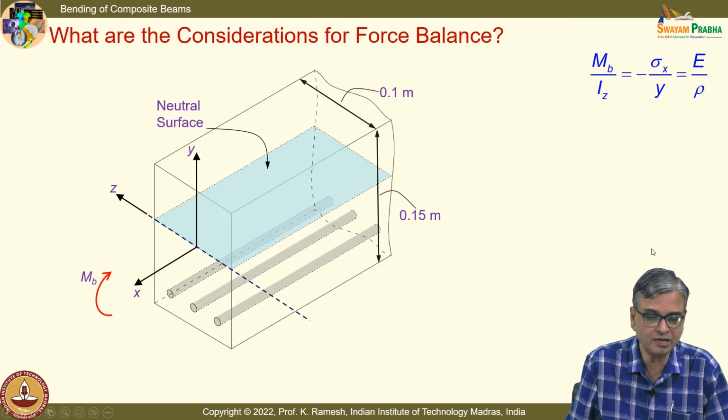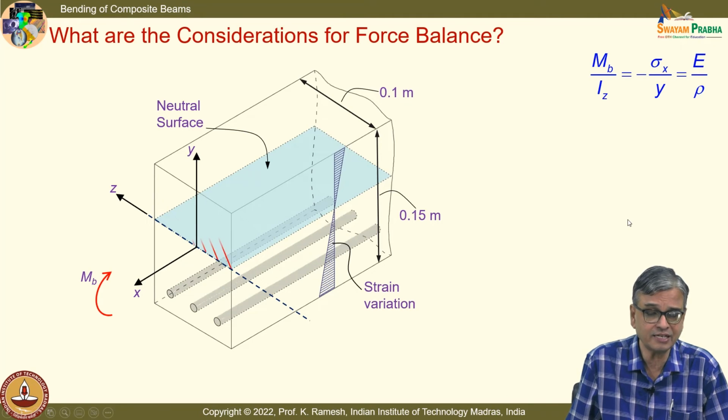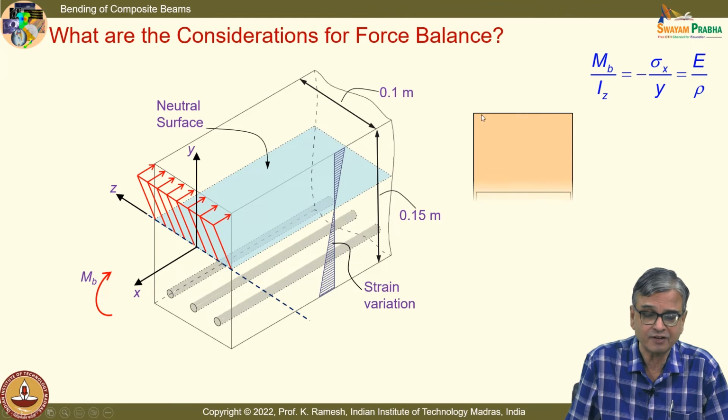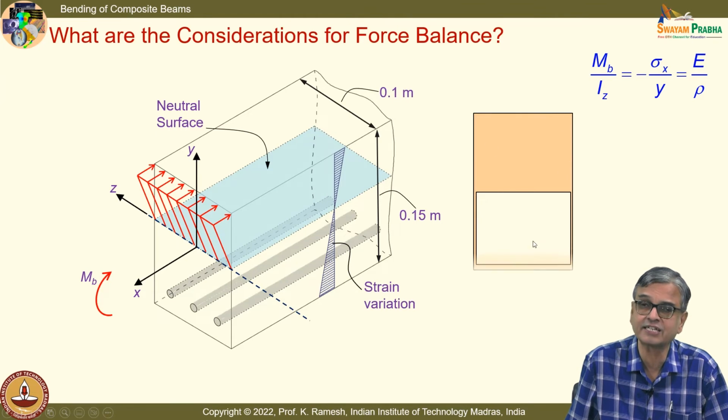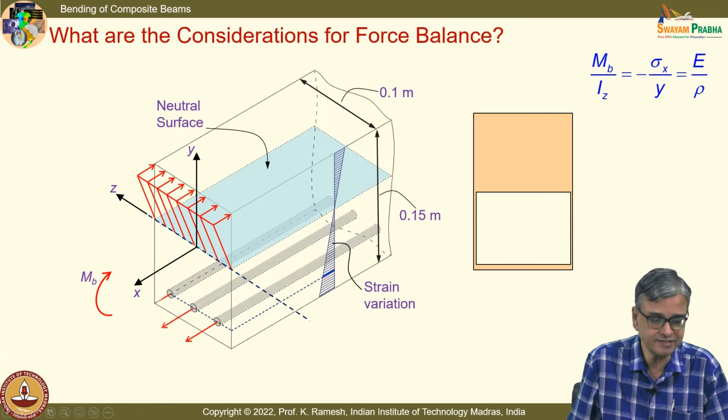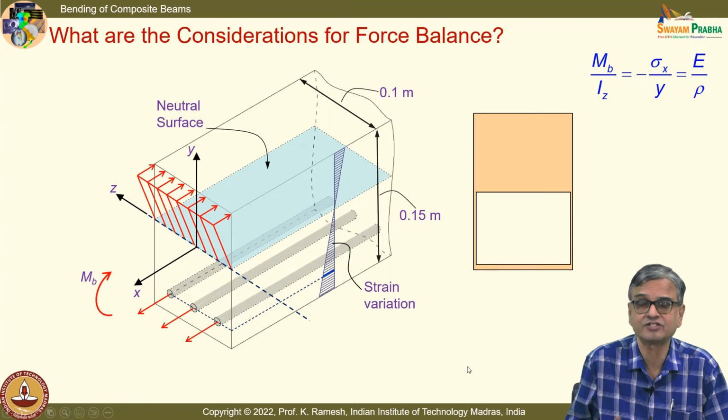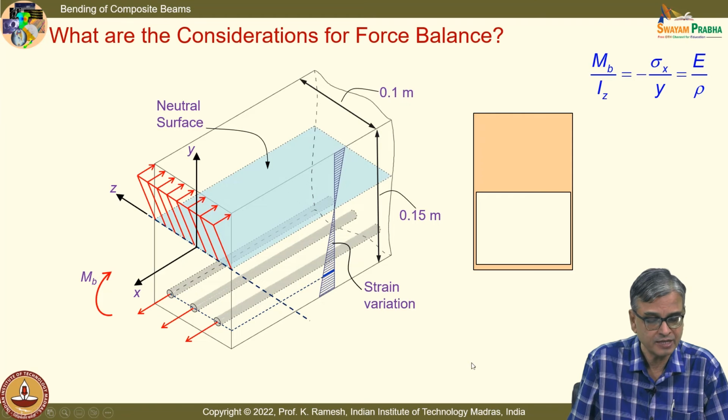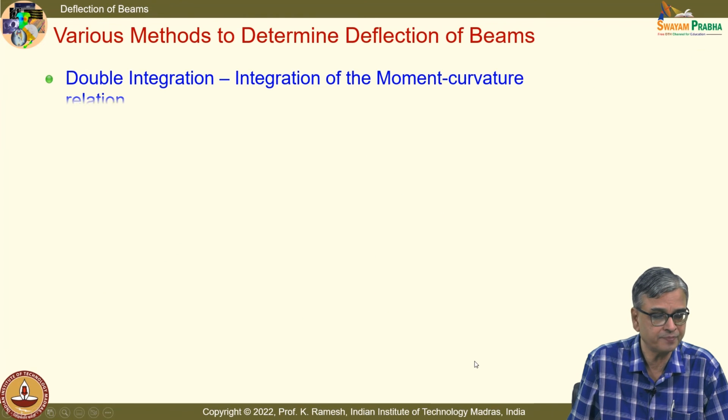And we have also learned how to analyze a reinforced concrete beam using the same flexure formula. We imagine that the concrete beam is like a section like this and a hollow section connected by a thin web. Okay, and that's how we have analyzed it. It's all engineering analysis because only the rods, steel rods take the tension load. Concrete is very weak in tension.